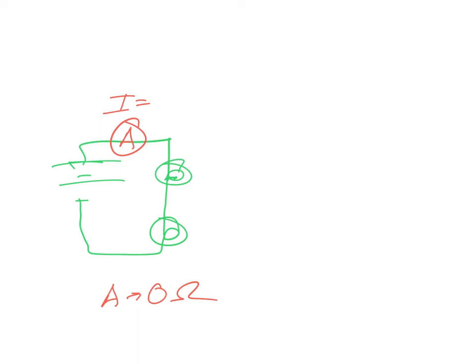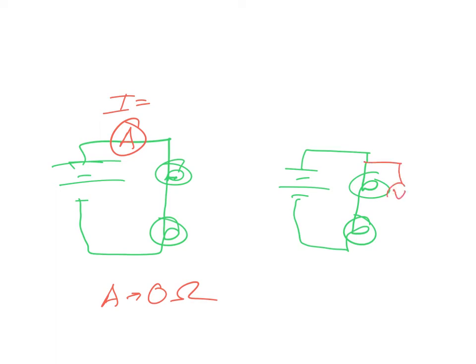If I want to get the voltage drop, it's always the voltage drop across one of your components. So that means the voltmeter has to be in parallel with that. And I could do one of these, or both of these. If there were multiple, it doesn't matter.